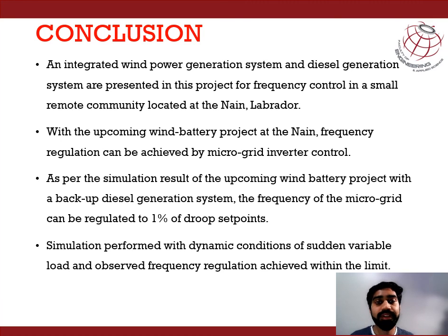So it will have issues of frequency regulation and voltage regulation if we have a high penetration of renewable sources. With this group control inverted microgrid method, it is simulated that the frequency variation and the voltage variation are within the set point, and that can be an effective solution to control frequency and to maintain voltage across the grid.